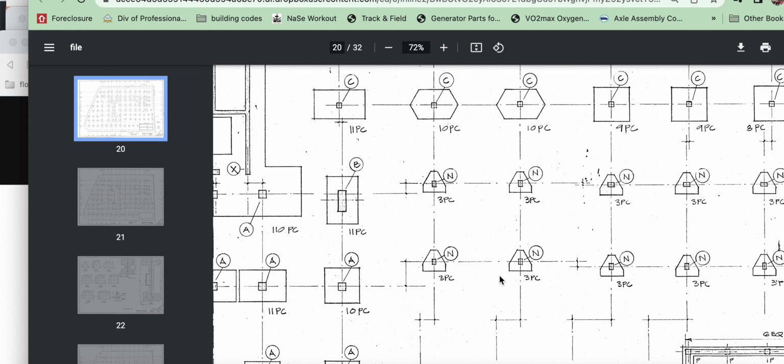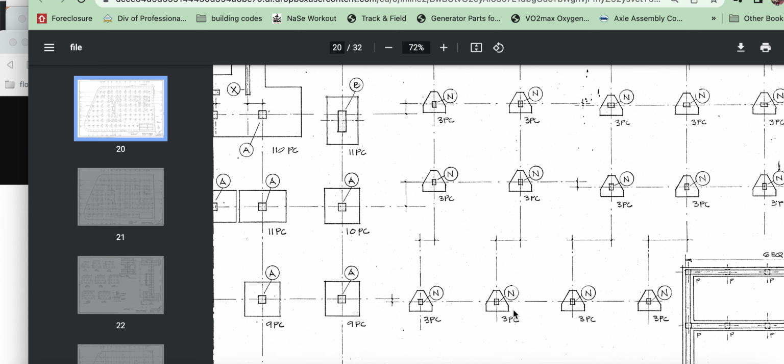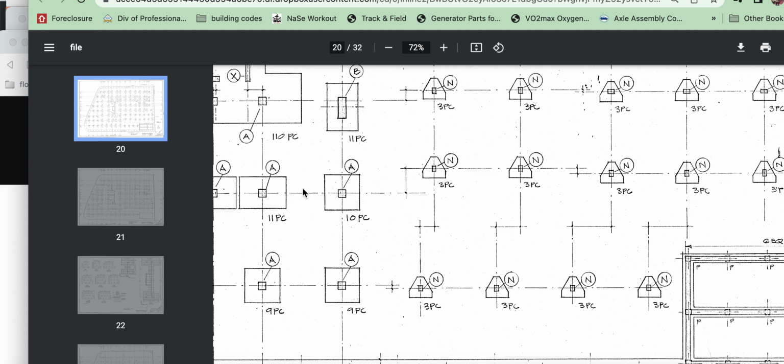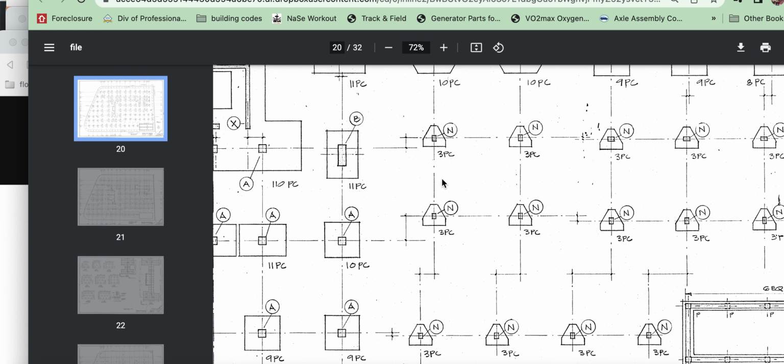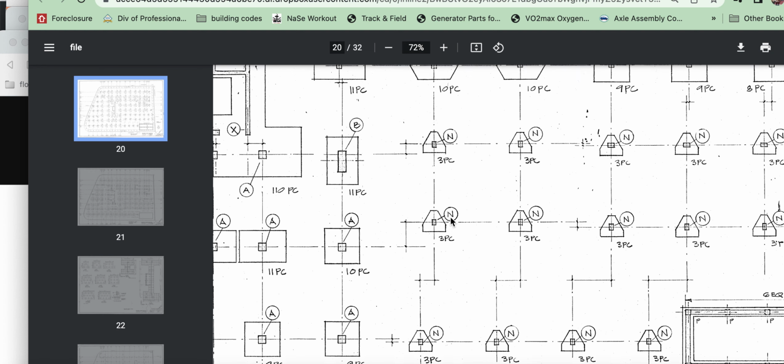These are the triangles. It says 3 piece, 3 piece, 3 piece. So the deck out here all had 3 pieces, and that's the shape I was trying to get across to you. They're all at 50 tons, so 150 tons each. Over here is where the cars are loading, planter box here. So you can do your spans. Remember, these are offset, so it's going to matter how the loading is.